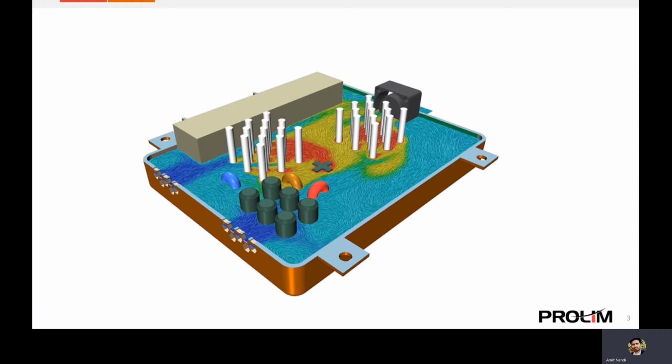He'll have to check different configurations of placing these vents with different positions, and the same goes with air vents with respect to shape, size, and position. He also has to check the performance with respect to different positions of the fan for better convection of the heat from the casing to the environment.